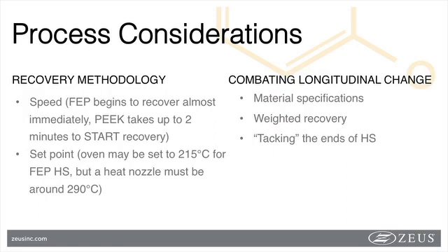On the other hand, if using a more concentrated heat source, for instance a heat gun, you may need to set the temperature on the controller to 290 degrees Celsius for an FEP recovery process, because you will move the heat source along the length of the tube, and the heat shrink may or may not reach the full 290 C in the process. Some processes have been developed where a very low heat-resistant material, such as lower degradation temperature polystyrene, has been covered with a very high temperature heat shrink, such as PEEK shrink, without any damage to the substrate. It is definitely all in the process.